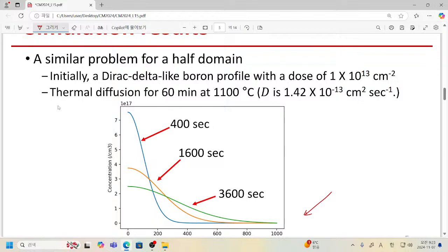zero flux, you can see that also the gradient of your impurity density C tends to be 0, because if we allowed such a high steep change here, then it would be related with high incoming or outgoing flux from this node into the substrate, but it is not possible. So yes, please understand the situation.